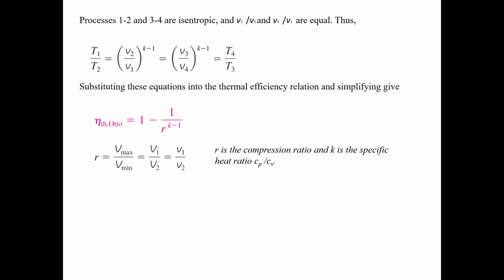r equals the compression ratio. According to this equation, when r goes up, your efficiency goes up. What we like to have is a higher efficiency. If the engine gives a higher efficiency, that's what we need. So if you want to make a higher efficiency engine, what you should do is increase the compression ratio, right? Isn't it?